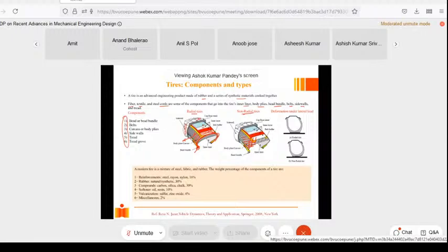So now what is the difference? So let us say you are turning your vehicle, right? Under that effect, you will see that the radial tire contact will remain intact with the surface, but in non-radial tires, you can see that the sides will lift. When the sides lift, you have a smaller contact area. It means the forces will be less, right? So that's the difference between these two.